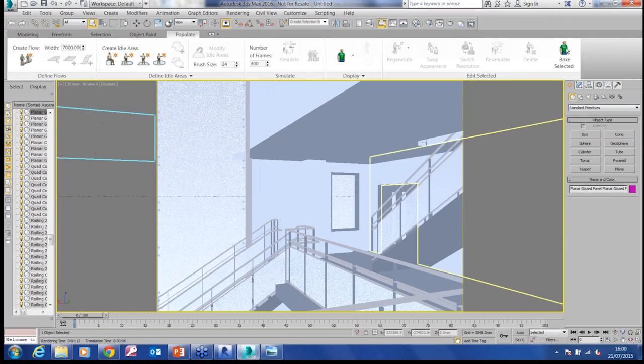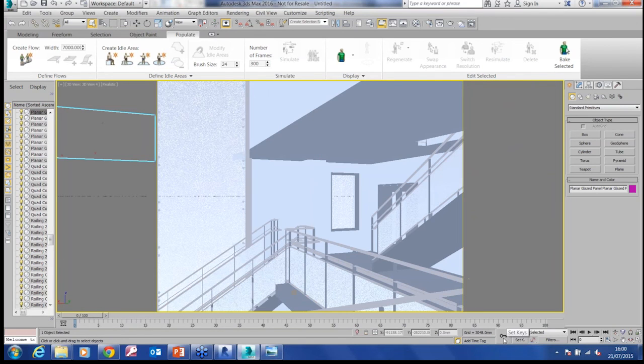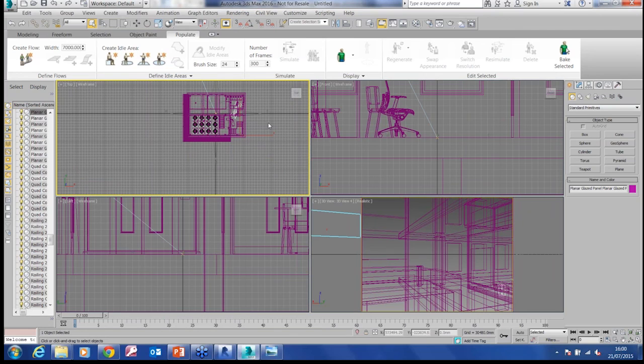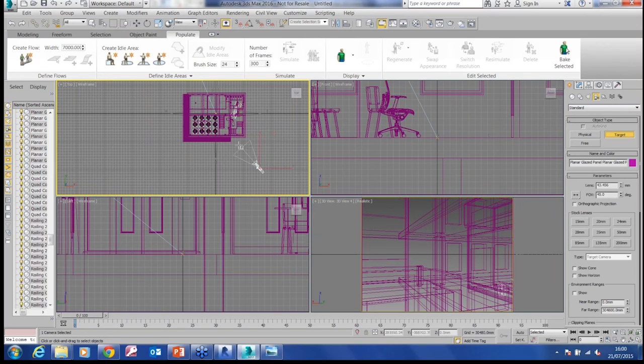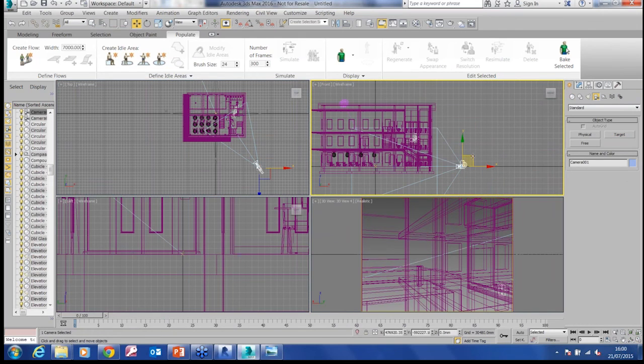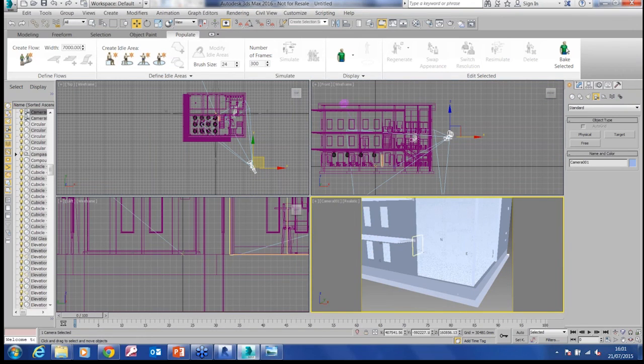Okay. As I mentioned before, all the cameras that we've got can be animated as well, so it doesn't matter where the camera is at the moment. We've got a full timeline here that we can scrub, and we also have the ability to then do keyframe animation. So if I was to just create a quick external pass just around this entrance, I can create a new camera, and we'll just create a new target camera in here. Let's just make sure that's actually where I want it to be. So we'll just maneuver that up, come to this one, change the camera to this new camera shot.